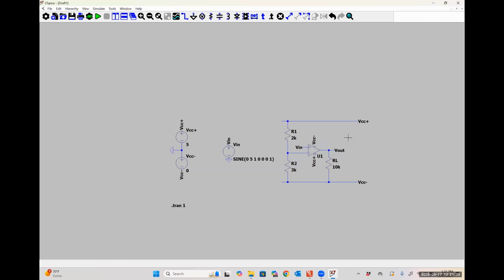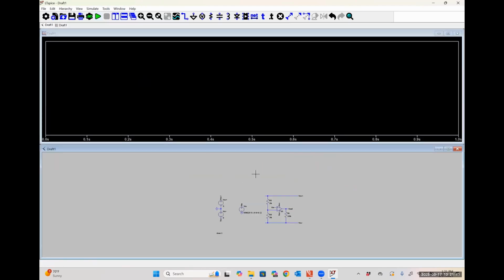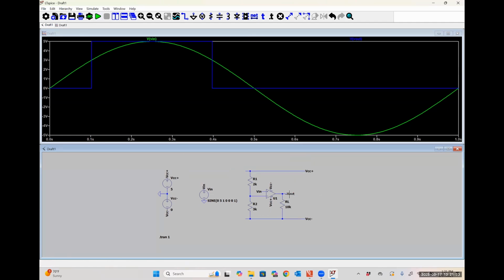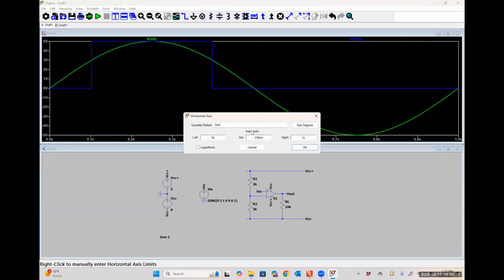All right, so here is our circuit. Let's simulate it. And let's look at our input signal, and then also our output signal. And it looks like now our output is going to 5 volts whenever our input is equal to or greater than 3. And then our output goes to our digital low whenever our input voltage is less than 3. And we can obviously look at that by plotting our output as a function of Vn again.